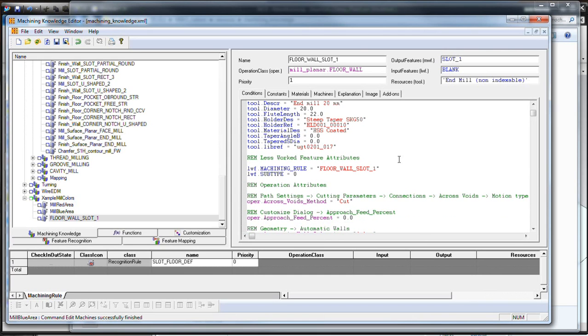When NX is looking at how it's going to machine a feature that it's given, it thinks about it in a very similar way to how a machinist thinks of a feature. You basically think backwards. You look at the final tolerances for, say, the diameter and position of a hole. If a hole has a high diameter tolerance, you might decide to ream that hole.